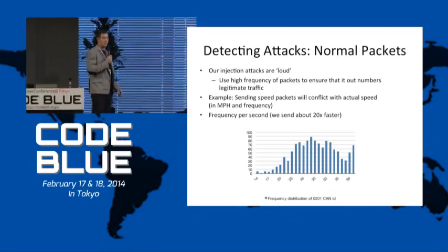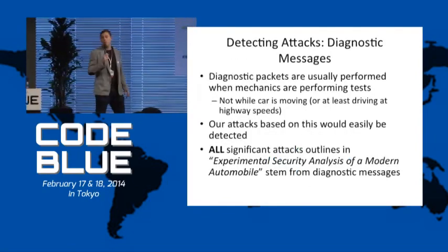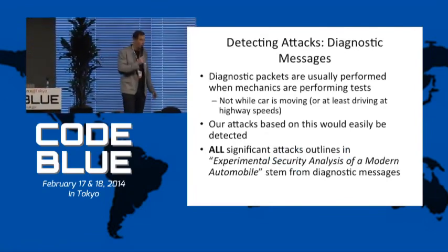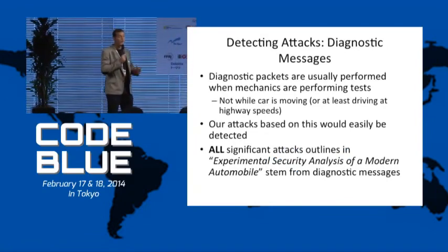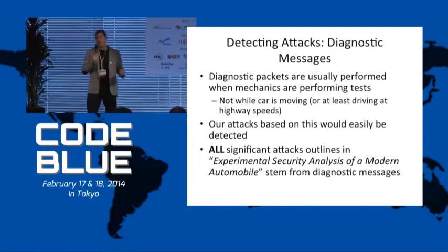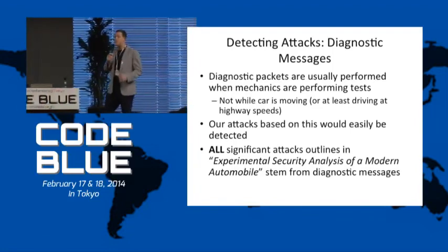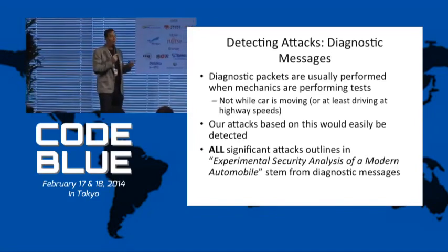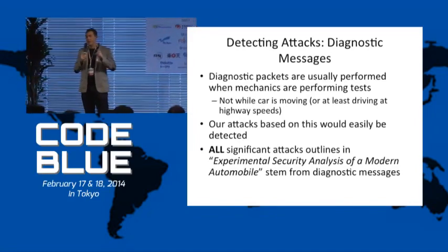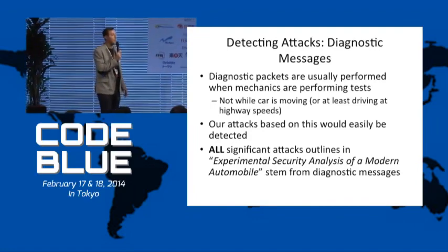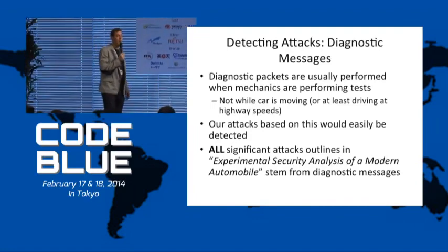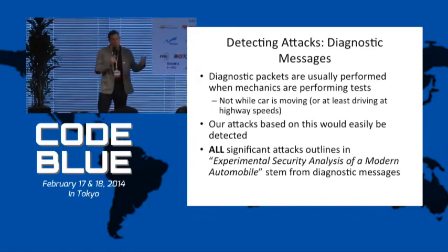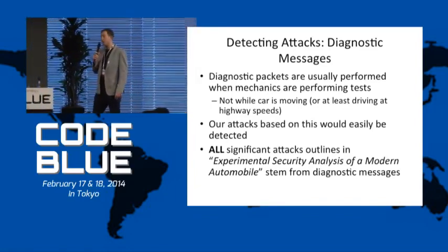Diagnostic messages are for mechanics. I know there are probably some that are used while the car is in operation for things like OnStar or SOS. I understand that you can't block all diagnostic messages, but at the same time, you could have a very small whitelist of messages that are acceptable to be seen while the car is in function. The rest, such as security access, probably can be done without.